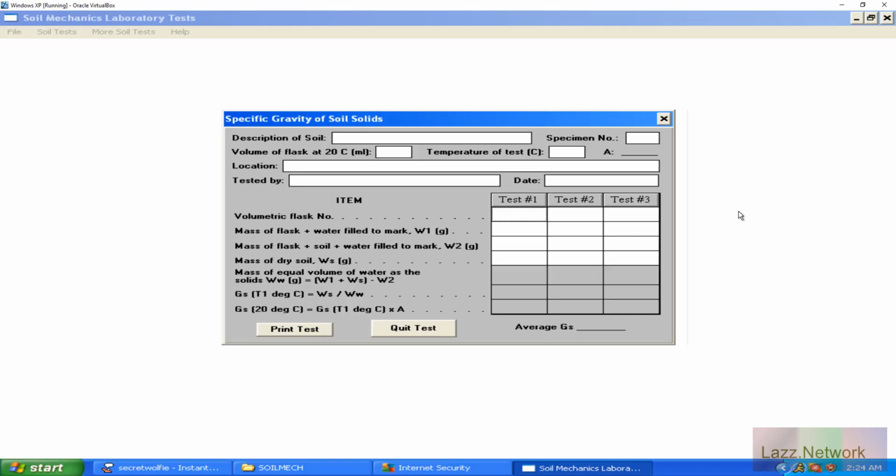typically for this test method, obviously you have your AASHTO and your ASTM method. This typically follows ASTM D854 and/or AASHTO's T100 test methods. At this current moment of me recording this, they are two drastically different test methods from one another. So obviously if you do an AASHTO T100 and somebody wanted an ASTM D854, you would probably have to redo the test again.